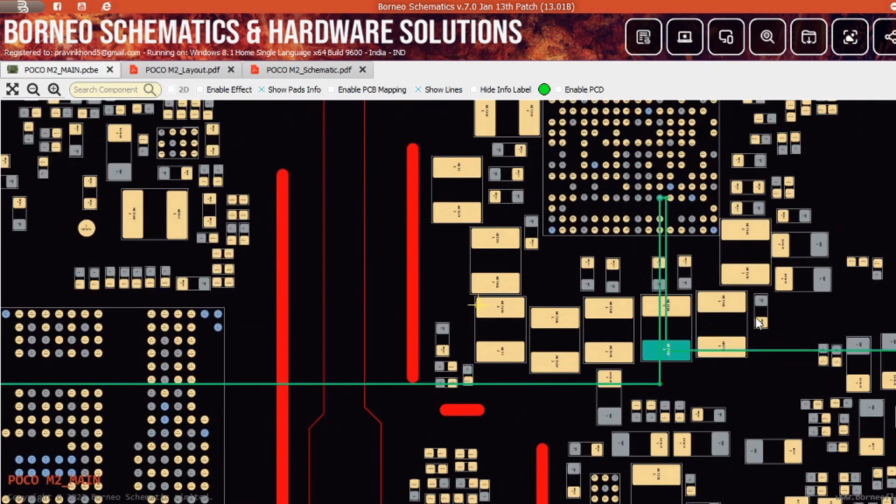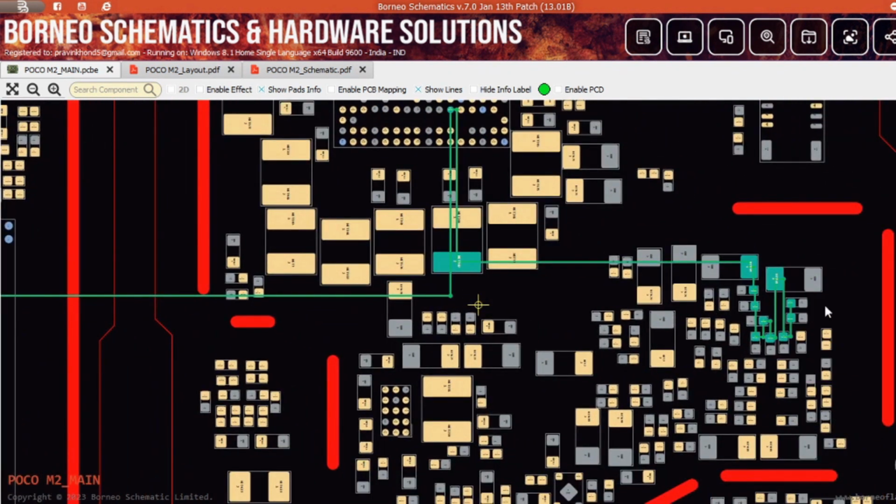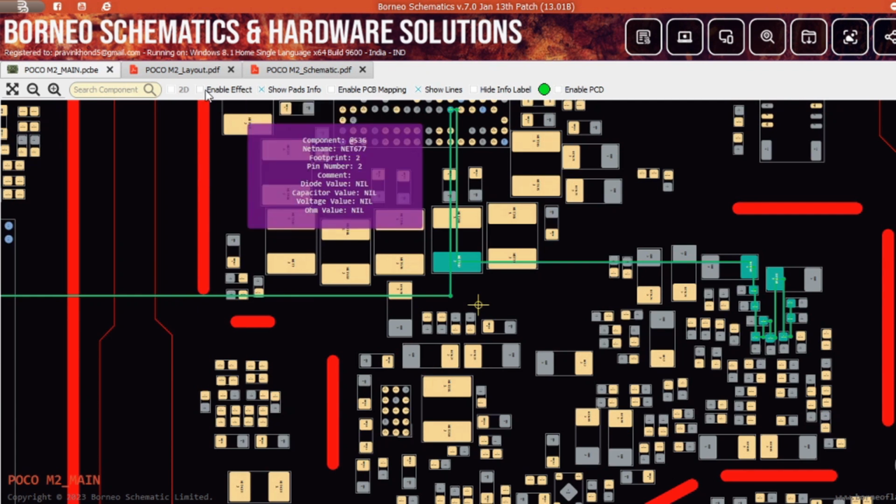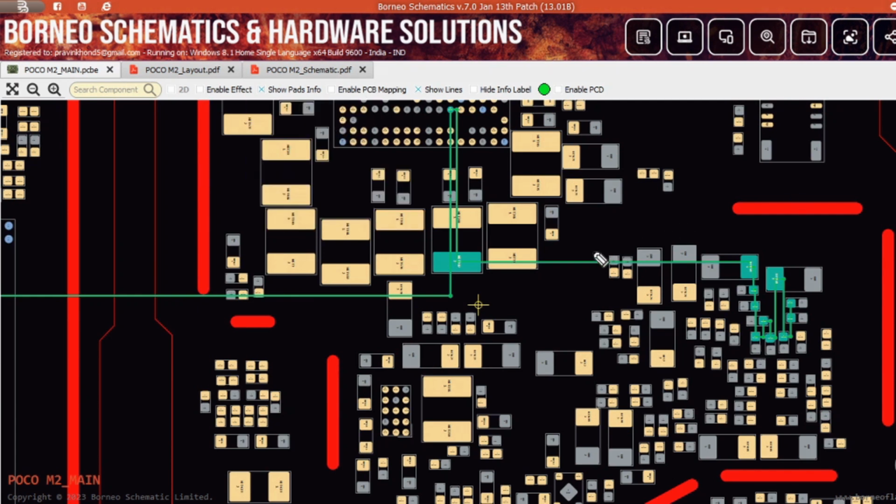Now in this line you will get a low reading, I mean to say a low diode value. When you measure the diode value in a multimeter, also in ohms mode, you can see most probably there is sometimes 15. In some lines you get 15, 20, right, a diode value. So some technicians get confused.